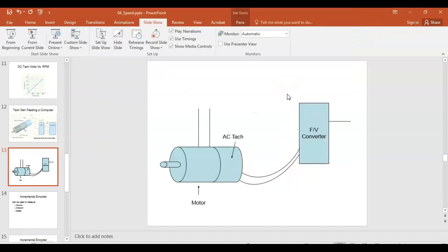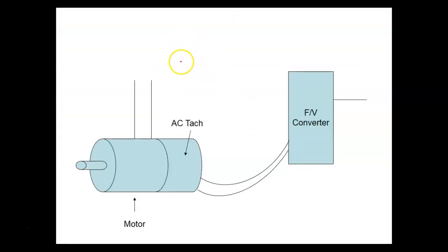So what I'm doing now is I'm measuring this. And this gets people killed. So this is very important that you understand this. I'm measuring AC. What would be the DC average of this right here? 0. So my problem is I have my meter on DC. For every plus we have over here, we have a minus over here. So if this is a plus one, then this would be a minus one. DC gives you the average DC value.